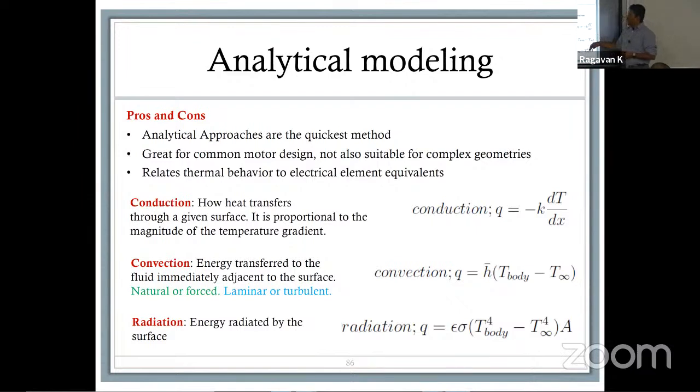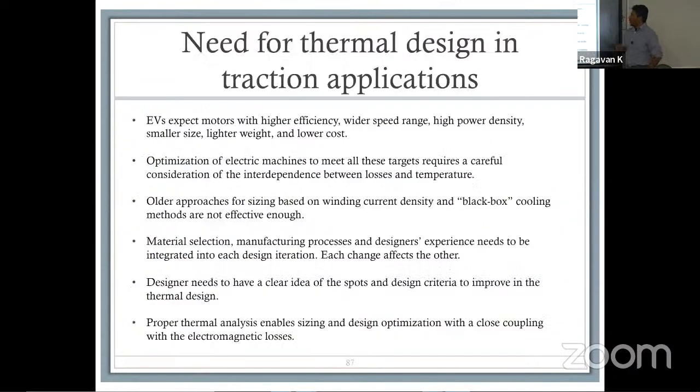You have specific equations that tell you. Analytical methods are always going to be faster, but they will have limits. If you are trying to do something very complex, let's say you are trying to even include something like nanoparticles to increase the conductivity of the coolant you're going through. I'm just putting it out there. I'm not saying that's what you should do. But if you do that, you might have a more complicated coolant or heat transfer capability, because now you have some sort of a colloidal solution. It's not a clear liquid. It's not a completely uniform fluid. So you would have to play through that a little better, in which case you might end up going to CFD, because that would be a much better way to analyze.